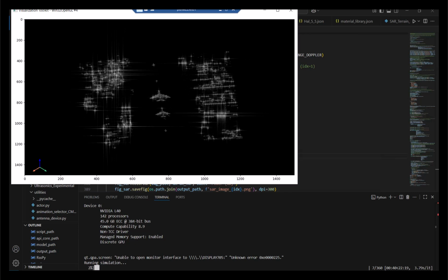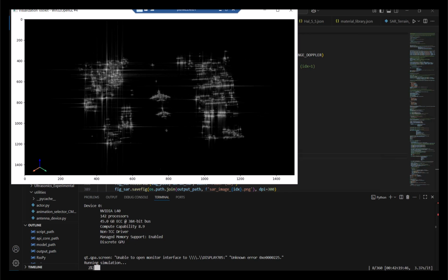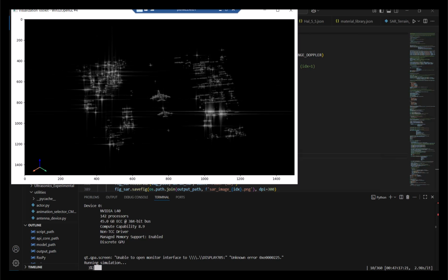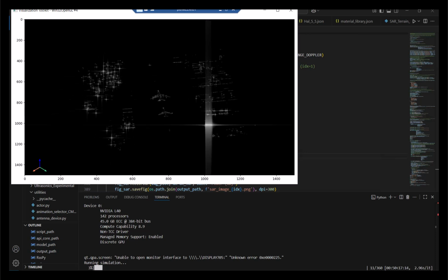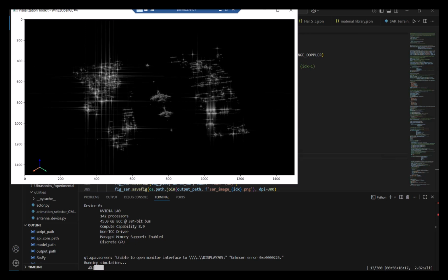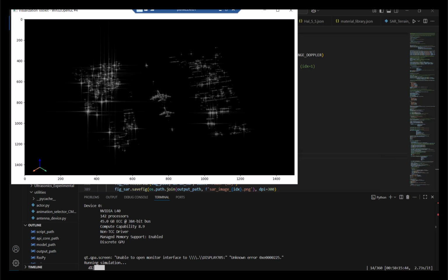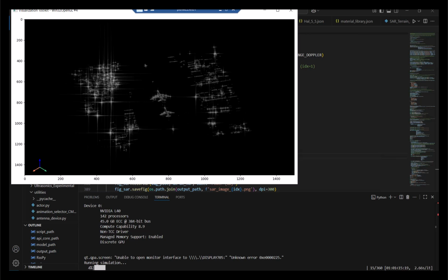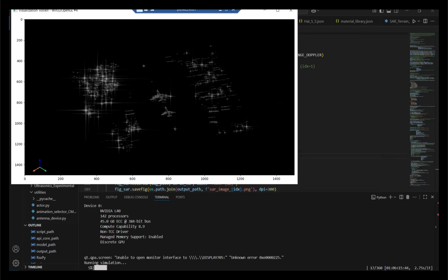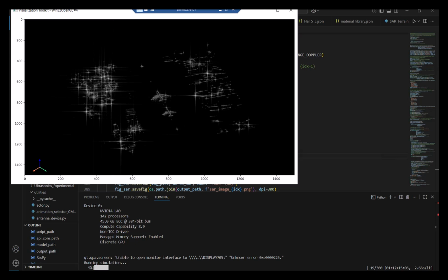And these are the building reflections which are coming up. You can see there are strong reflections from the building edges. Those are mainly because of the building's sharp edges creating that high spot. This can be reduced and the image can be even smoothened out if you apply some windowing function. We'll run one more case with another window.